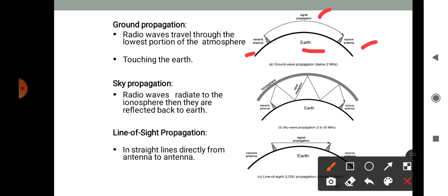Higher frequency radio waves radiate upward into the ionosphere and are reflected from it. While in the ionosphere, the wave is strongly bent and refracted, ultimately back to the ground, and from a long distance away it appears as a reflection. Long ranges are possible in this mode, hundreds of miles. Sky waves in this frequency band are usually only possible at night, when the concentration of ions is not too great, since the ionosphere also tends to attenuate the signals.